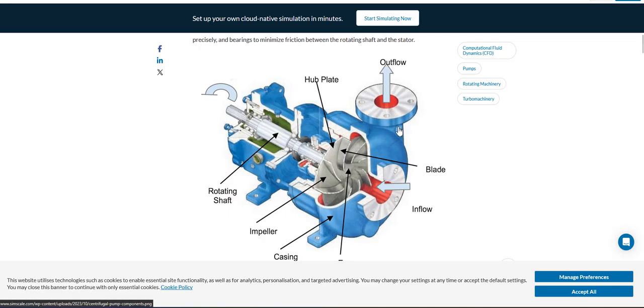So once again, the case. I haven't seen a case made of aluminum before. Is there any possibility to have additive manufacturing here? The answer is probably yes. For example, the arc welding additive manufacturing process. I saw people making the impeller using the arc welding additive manufacturing process. They just make the shape and then machine it to get the final geometry.